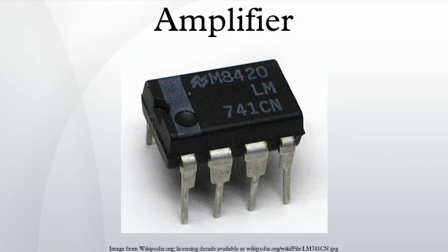Additional classes. There are several other amplifier classes, although they are mainly variations of the previous classes. For example, Class G and Class H amplifiers are marked by variation of the supply rails following the input signal. Wasted heat on the output devices can be reduced as excess voltage is kept to a minimum. The amplifier that is fed with these rails itself can be of any class. These kinds of amplifiers are more complex, and are mainly used for specialized applications, such as very high power units.